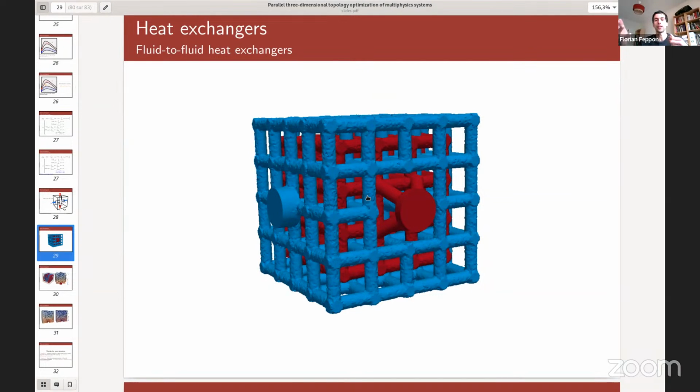In fact, we need 2 level sets only in order to impose the distance constraint. But this is purely the modeling of the distance constraint with a penalty functional and the computation of the derivative of this functional. So this uses the computation of signed distance functions, which are somehow also level sets. But for the shape updates, we don't need 2 level sets. We need only 1 level set. Okay, very interesting. I'll be looking in more detail at that work.